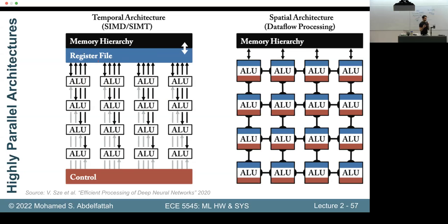What you realize about this architecture is that the main point of contention and point of contact is this register file. That's part of the reason why GPUs have a very large register file, to absorb all of that bandwidth of all of those CUDA cores or ALUs or PEs, right?